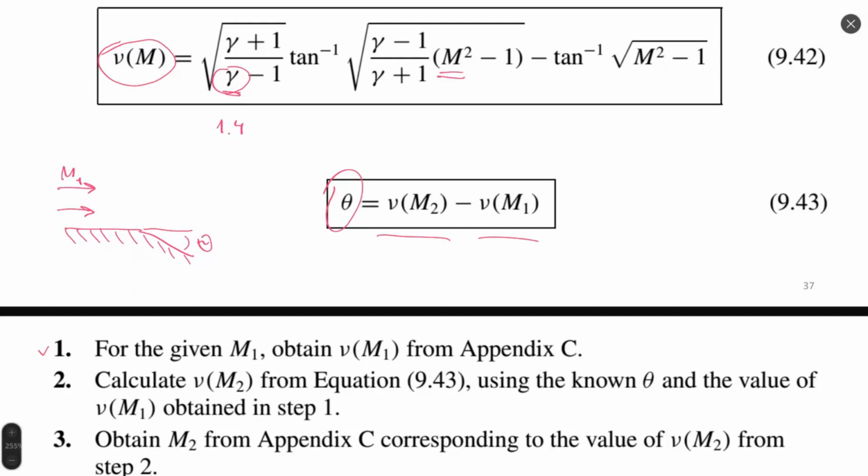And usually we can have gamma for hot gas, for gas inside the rocket combustion chamber, for example, 1.1, 1.15, 1.2. For colder gas, like air, already 1.4 values. Could be bigger.